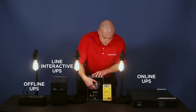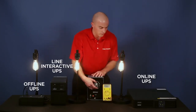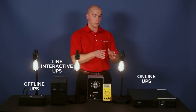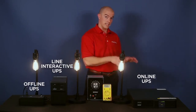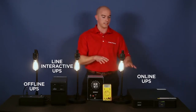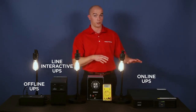As we continue to lower the voltage to 80 volts, 75, 70, 65, and finally 60 volts, you'll see that the online UPS never fluctuated the consistent power it was supplying to the load. This is because it is converting AC power to DC power and back to AC power consistently, isolating this lamp from any anomalies the utility power would show.